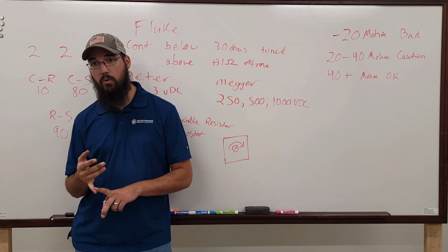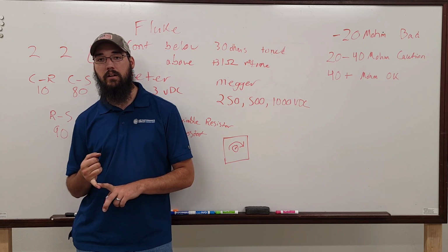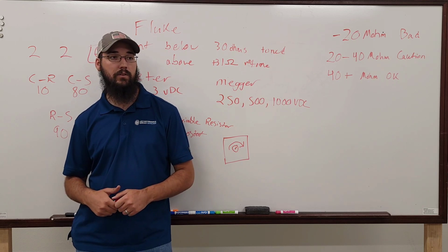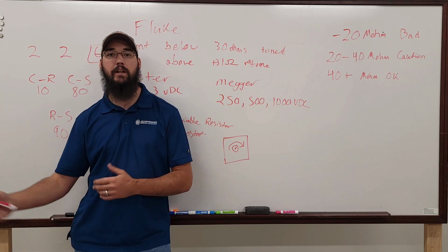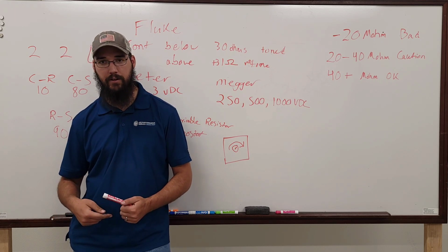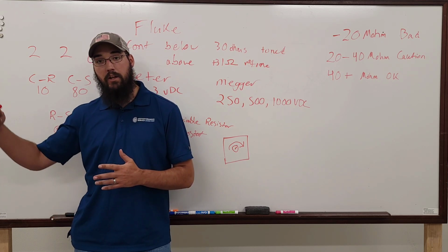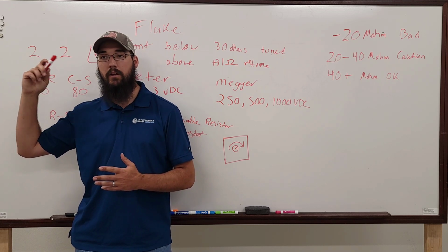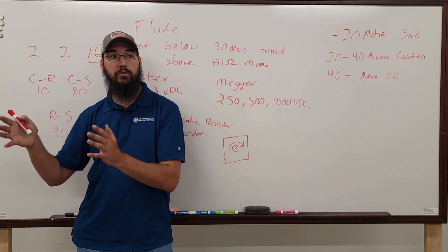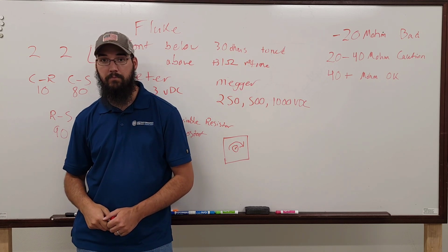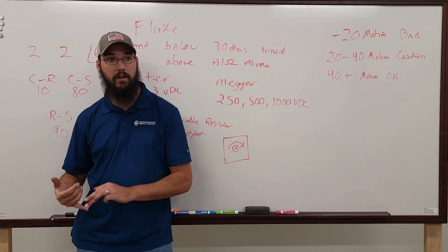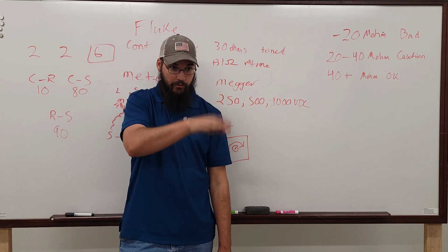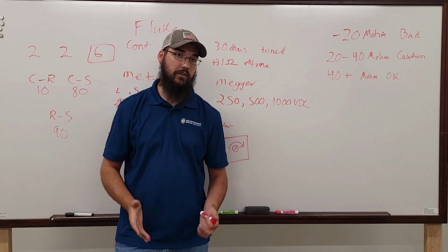Even if you show bad, say they're only slightly bad bearing readings, so say they're a 0.5 or 0.6, they're right there on the edge of condemnable on inner and outer. But yet your vertical, horizontal, and axial are all 2 and above, okay? Don't just immediately condemn those bearings. If they're not making noise, if you're not having other issues, but you can look at that motor and watch it sitting there doing this the whole time, that's not necessarily a bearing problem.